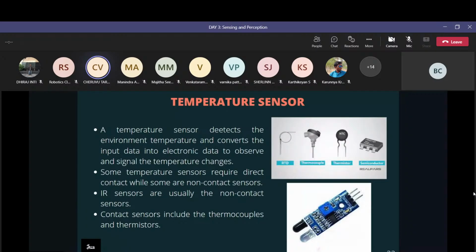To detect the temperature changes in the surroundings, its resistance will be continuously changing. It needs an external electrical current, which is applied and causes a change in the voltage. So this RTD will be connected to some external electrical current source. That source will bring some voltage difference, which will result in some resistance change. With the help of this voltage difference generated and the resistance change caused by the external current you have supplied to this device, you can identify the temperature change in the environment. So that's the basic working principle of the RTD.